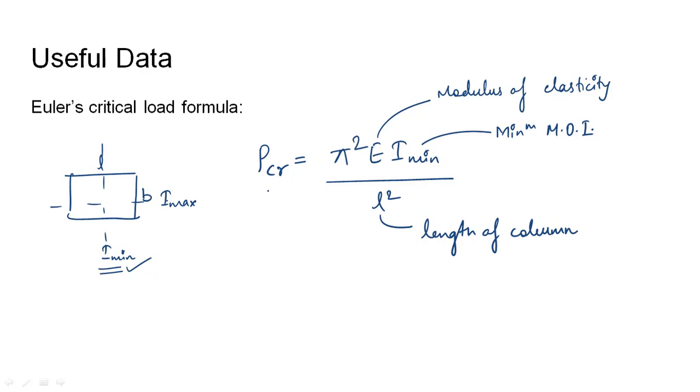This equation assumes that both ends are hinged. In case both ends are not hinged, an additional factor of k is introduced in the equation, but it won't be needed for this question, but should be kept in mind for other questions.